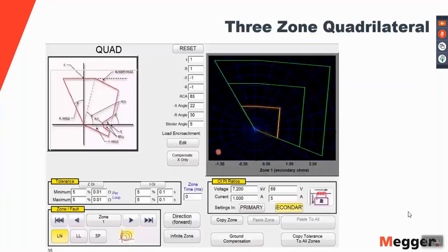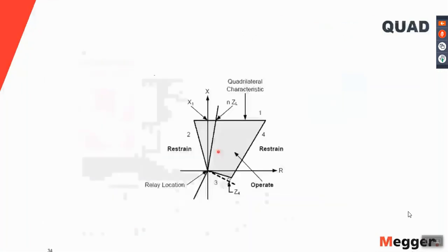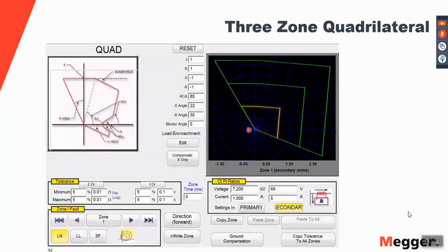And the good news is that you do not have to be an expert trigonometric wizard to calculate all the different points and whatnot. Both relay manufacturers and test set manufacturers have devised tools that help you by simply configuring the extreme points of the characteristic.